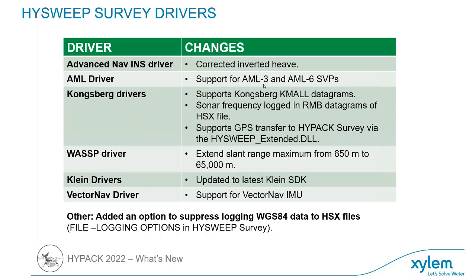Yeah. And then some more updates for the HYSWEEP survey device drivers too. So a couple fixes like the Advanced Navigation INS driver. We're supporting the new AML 3 and 6 SVPs right in HYSWEEP, so you can import that right into the HYSWEEP survey. It gets embedded in the raw file. It's pretty nice. We updated the Kongsberg drivers, so we support the KML datagrams.